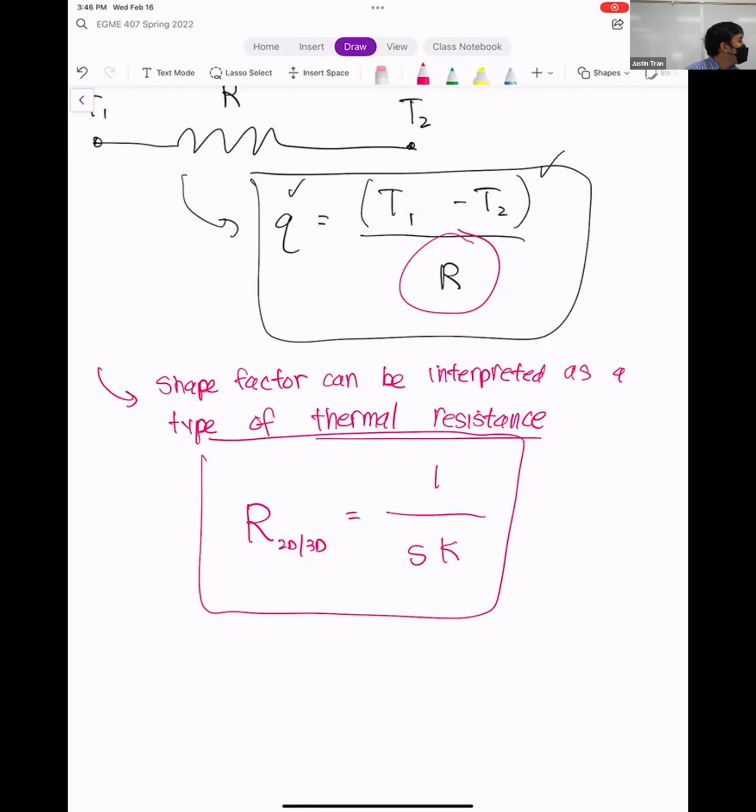I had a question about contact resistance. When we create the thermal circuit, is it in parallel? It's in series. And then how do we account for every single iteration? The contact resistance is not a really strictly measured thing. It's meant to represent that when two things are in contact, the overall effect is like an additional resistance. So this contact resistance is like an average.